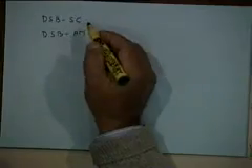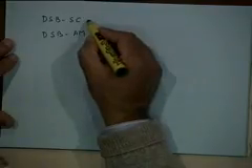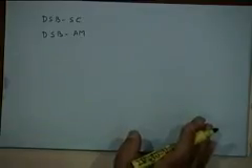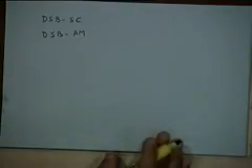What are the pros and cons of these? Bandwidth efficiency is the same for both of them. Right? Both of them would require twice the message bandwidth as the transmitted bandwidth, right. So, there is no difference in the bandwidth efficiency of the two waveforms. However, in terms of power efficiency, which one is better? DSB-SC is much better, right?